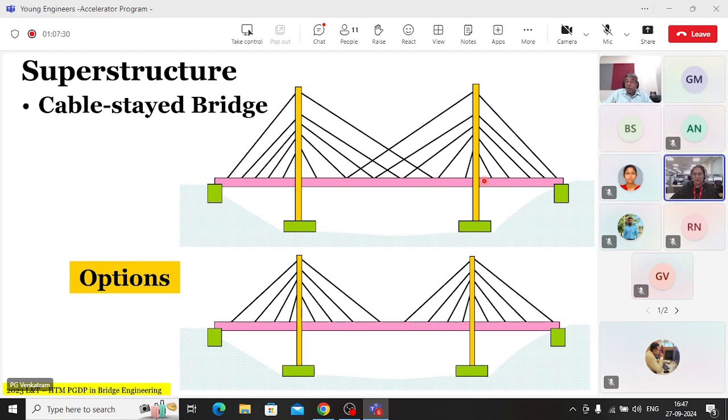Huh? No, 2 is stiffer just because of that bending. Look, don't confuse load effects with stiffness. They have nothing to do with each other. Stiffness is an inherent property of a structure. So I'm asking again, this deck versus this deck, which has more stiffness?